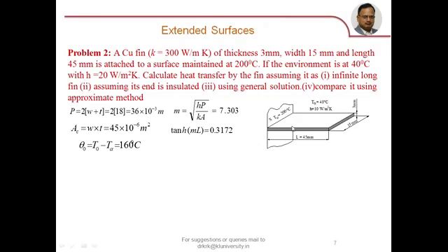It's a very interesting problem which will include all the 4 cases we have considered, and let us see which one will give you the exact or correct solution. Again, I need not specify, we are assuming it as a one-dimensional problem. We are considering only conduction and convection and neglecting radiation. We are assuming steady state conduction, and we are not considering thermal conductivity variation with temperature, and we further assume a uniform cross-sectional area of the fin. These are the assumptions we have taken in this particular case.